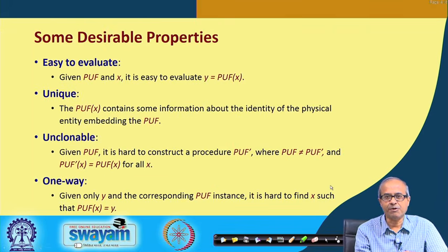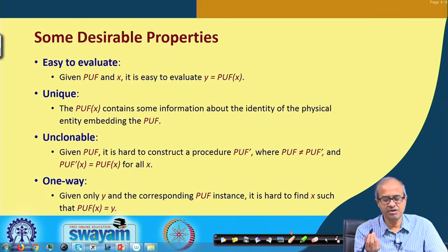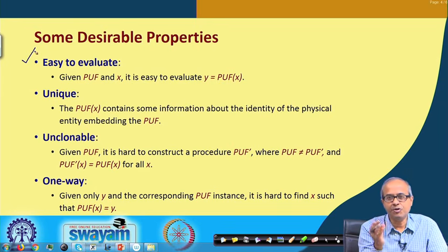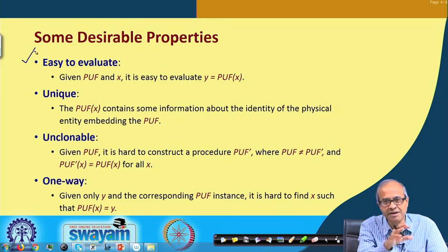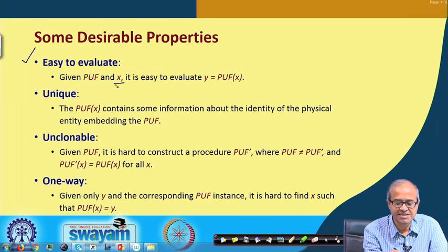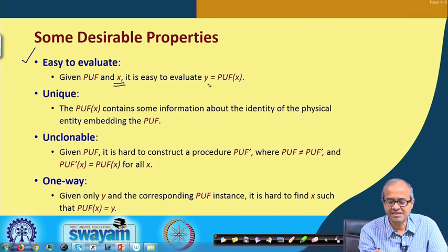Some of the desirable properties of PUF are mentioned here. These are quite obvious. First, it should not be too difficult to evaluate in terms of the challenge response. Suppose I give a challenge X, the response Y should be easy to compute. Secondly, for a particular device, the challenge response properties should be unique.